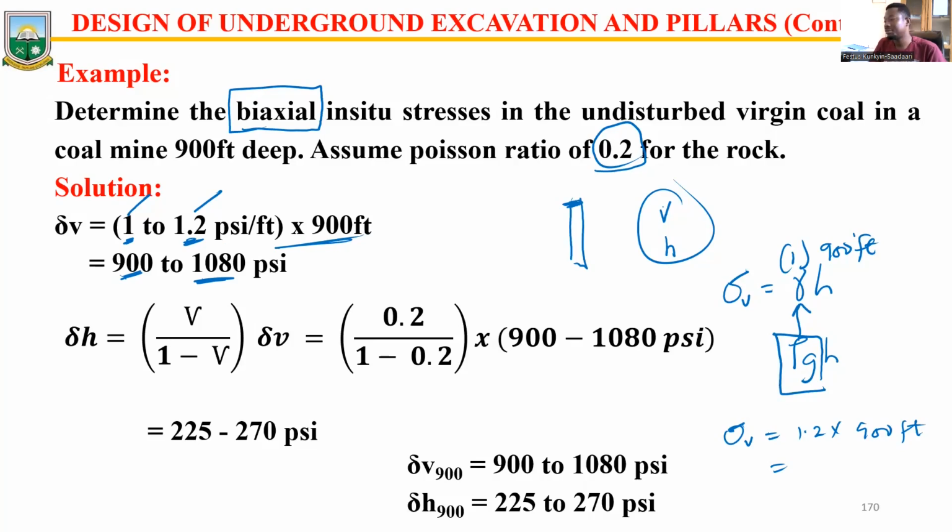You are done. You have been able to get a fair idea. You have not started mining, but you've been able to predict what pressures you expect to exist when you go to a depth of 900 feet to go and work. And this is what we term as the pre-mining stresses. Then, whilst you are there, you should expect corresponding forces on your x-axis acting on the pillars or the walls.